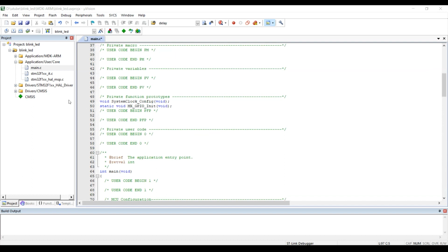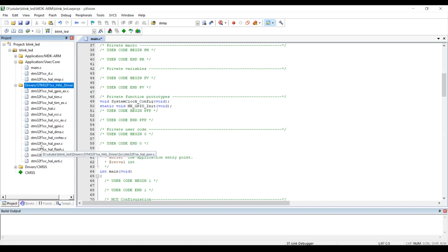So this is our main.c. This file here is related to interrupts, and we're working with the HAL libraries that are provided here. Of course, you could write your own functions by referring to registers, and if you want to do so, you have to refer to the reference manual, which is released by ST company itself. But it's hard work. However, it is so fun, and I suggest you learn it if you're interested. But it's something that ST engineers have done before, and they've created libraries for you so you can use them and not go to register levels and bother yourself. It is much easier to use these libraries.